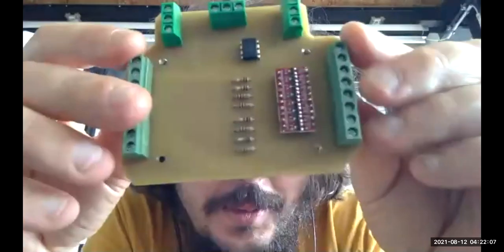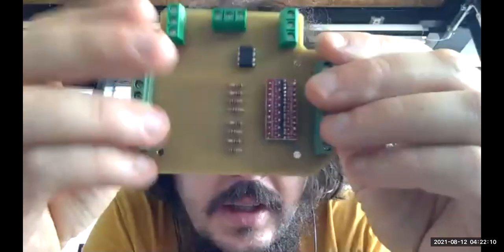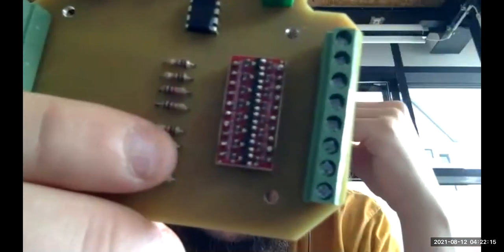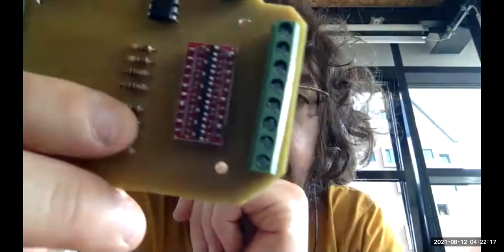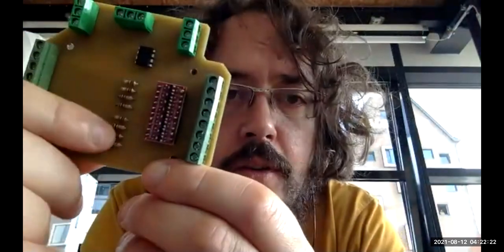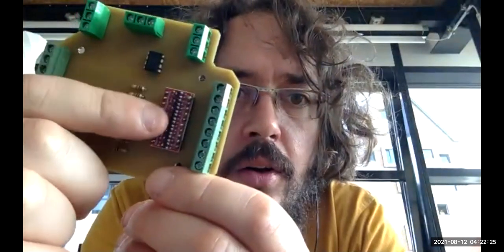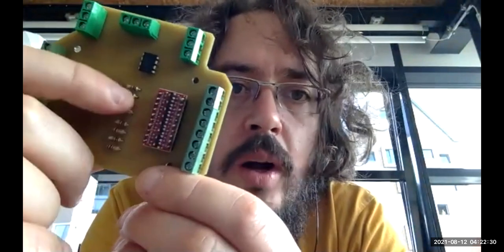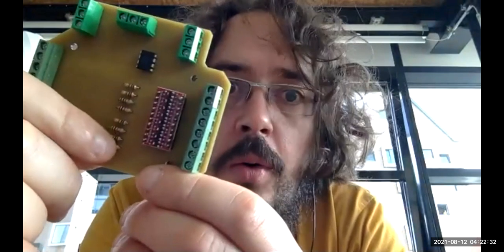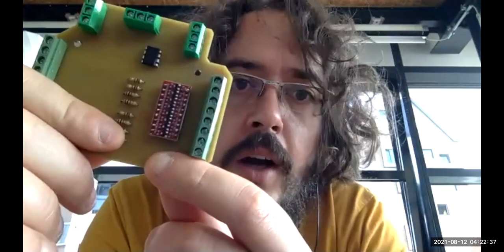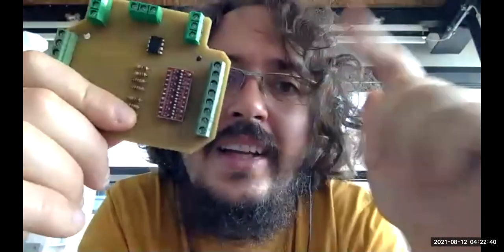These are very simple PCBs that I made. There is a logic converter on board, this red one, which is a ready-made component that just uses a couple of transistors for doing that. And the trick to increase the frequency of the output is to put pull-up resistors at the end. This one has 10 kilo ohm pull-up resistors on the output, and we put in parallel a 1 kilo ohm resistor to lower the resistance of the pull-up, to have stronger current in the pull-up of the output. This will raise the level very quickly.